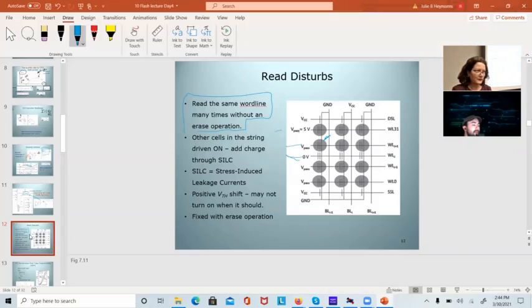There is an effect like this in DRAM. It's called row hammer, and hackers use this to basically disturb the rows adjacent to it. They turn on a row and leave that row turned on, which means you can't refresh it. And they write to it hundreds of thousands, millions of times. And so they're reading and writing from this row, and just that extra energy in the system is enough to possibly flip bits in adjacent rows. And yeah, I think Cambo talked about row hammer briefly at some point. Okay.